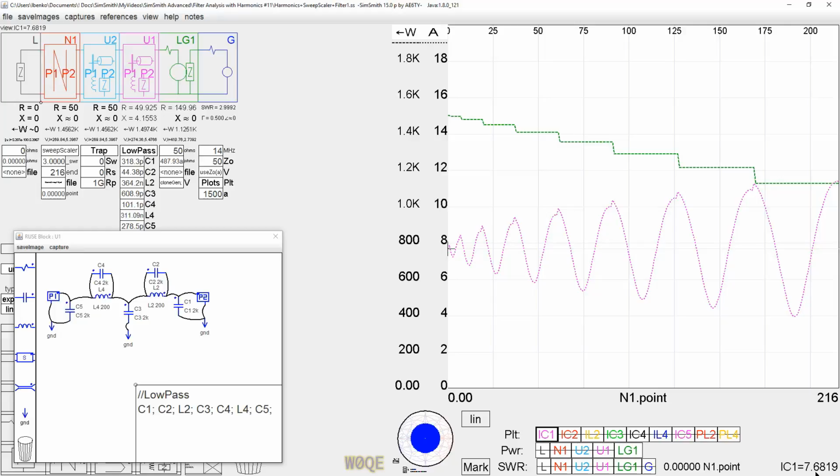And you might say, well, that's not a big deal. But remember, power consumed in a component is proportional to the current squared. So we take 8.3 and divide it by, say, 7.6, and square that number. We get about 20% more power dissipated in that component. And we can do that for every single component in the circuit.